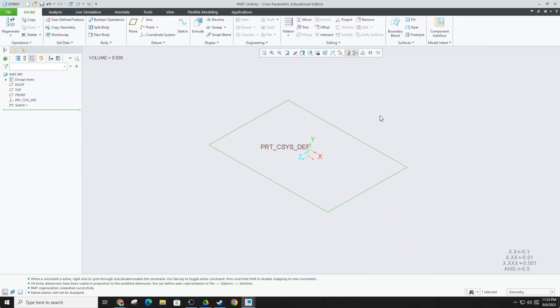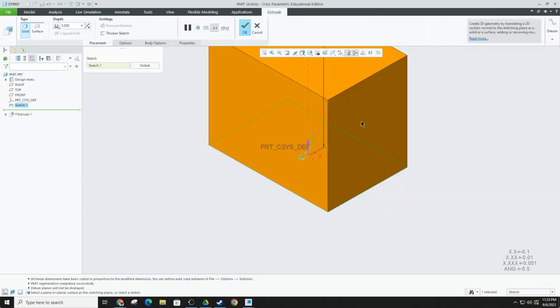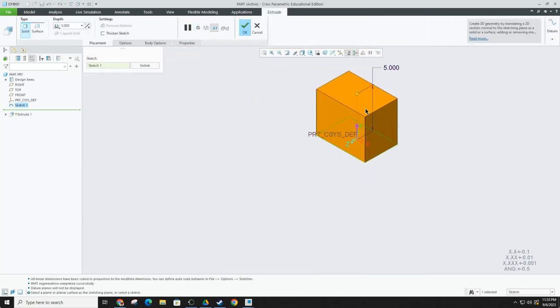One of the things that we can do is clicking this and then using the extrude button. When you click that, it will now have a height or a depth. So before on a sketch, you only have a length and a width. Now you can control the height. You can drag this blue, hold it down, and you can raise or lower it as you please. You can actually double click this measurement here and then put exactly, let's say 3, and press enter. So you now have a box 6x4 and the height is 3.